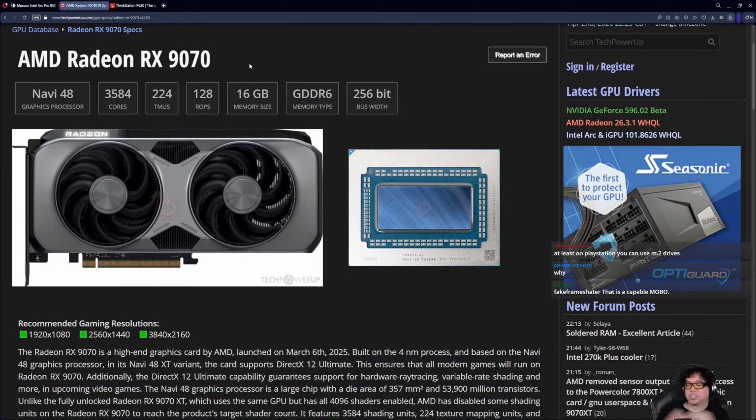This is obviously true for someone upgrading regardless of the socket who has to go to the new socket. Like if they're on AM3 or AM4 and want to go to a modern DDR5 platform with PCI Gen 5 capability, they have to change sockets and do a new motherboard upgrade.